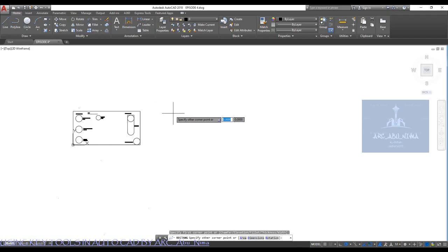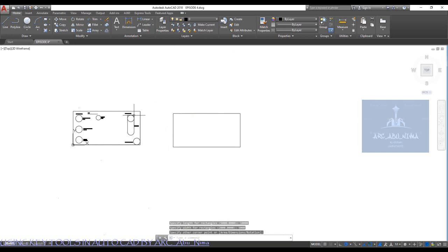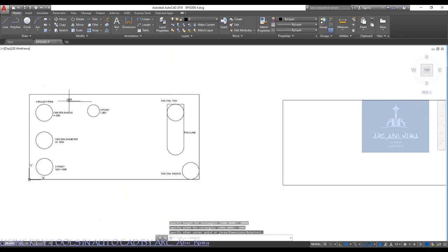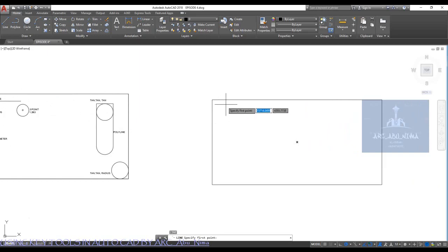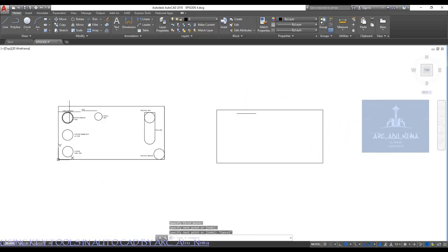We enter our dimension D, specifying the length, let's say 10 meter, the breadth or width, 5 meter. So we already have what we have here. Also for the line, you can just take your command L and draw at any point. So that is the line we have.